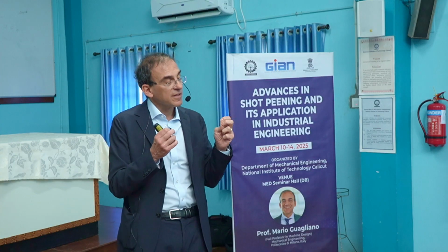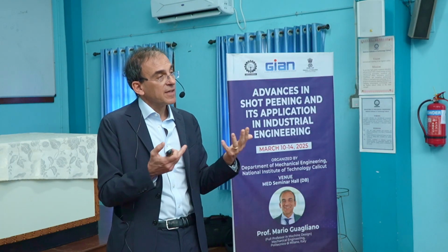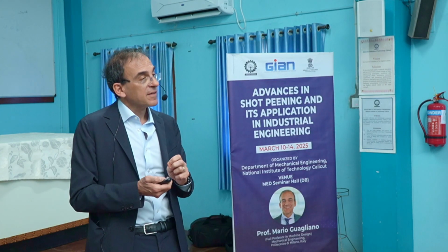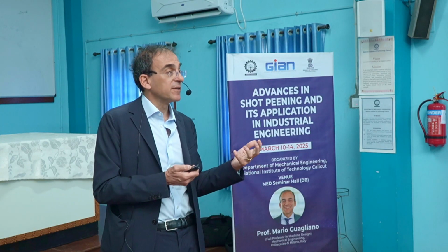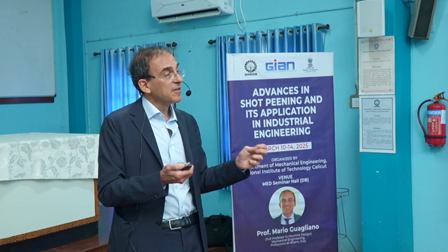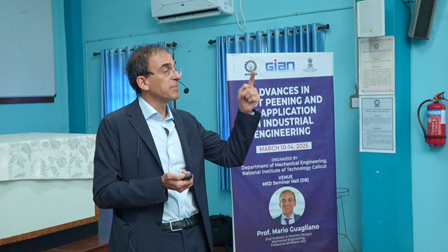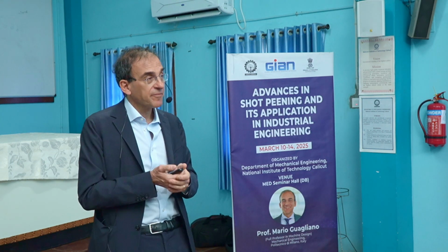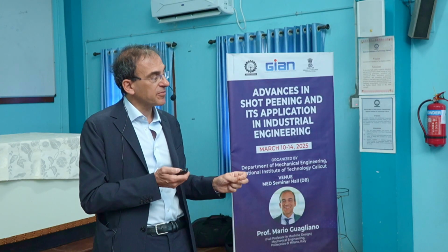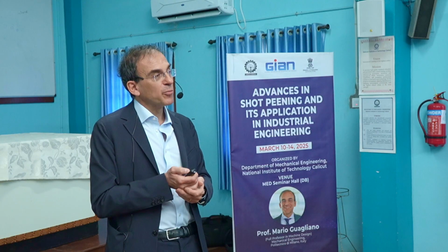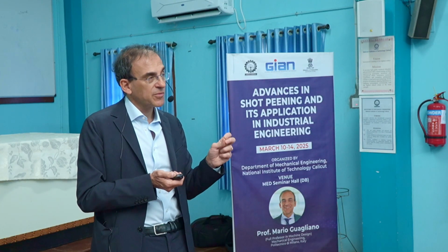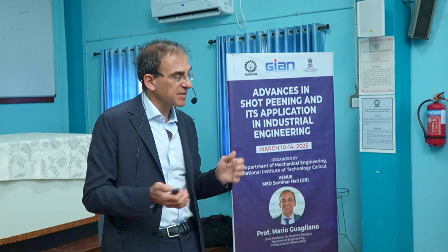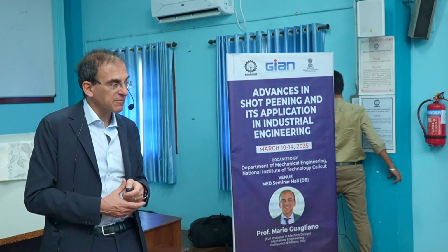The final residual stress distribution due to shot peening is the superposition of these two effects. For some parameters, the Hertz effect will be dominant, with a peak under the surface. For other parameters, the peak can also be on the surface. If we consider steels, many times the peak is under the surface. Talking about aluminum alloys, it's not rare to have peening parameters that induce a peak at the free surface. But anyway, this is a consequence of the applied parameters.